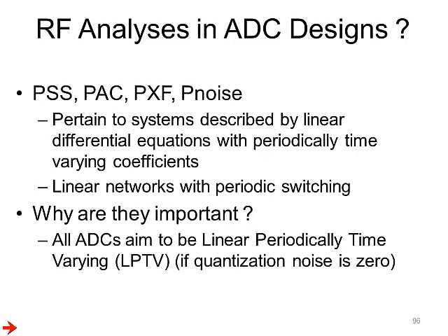Periodic analyses pertain to systems described by linear differential equations with periodically time-varying coefficients. In our line of work, they most probably refer to linear networks where there's periodic switching activity, like switched capacitor circuits. And why are they important? Recall that all A to D converters are fundamentally linear, periodically time-varying systems if the quantization noise is set to 0. That's because of the sampling operation inherent in every analog to digital conversion.